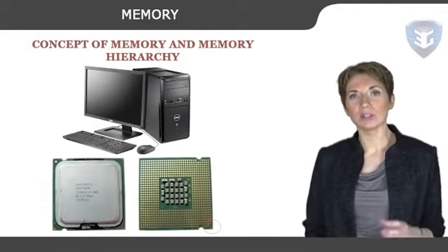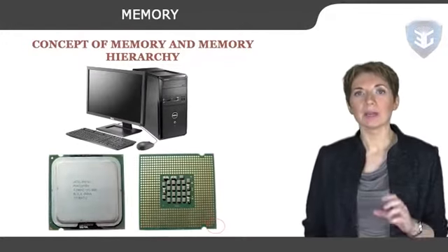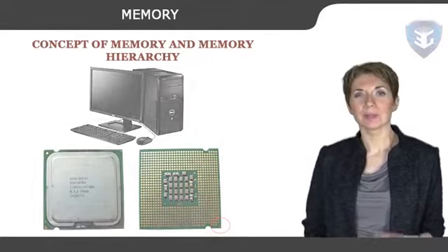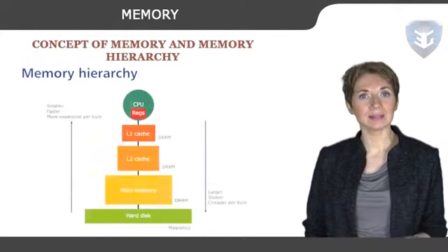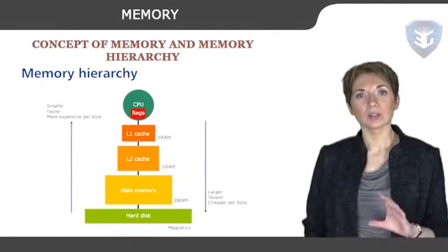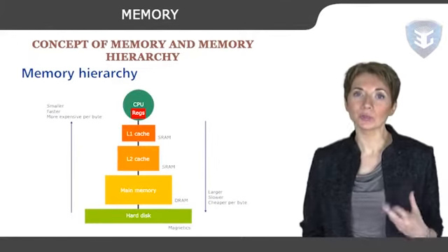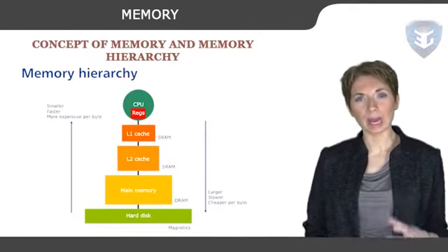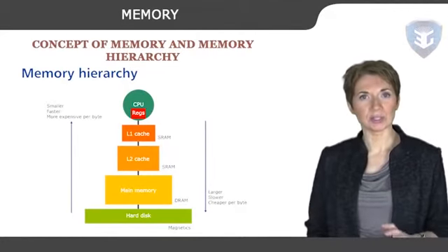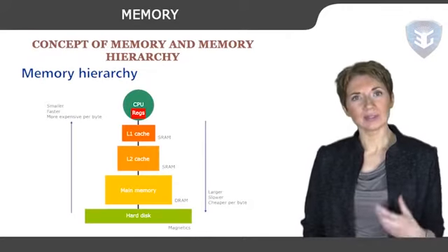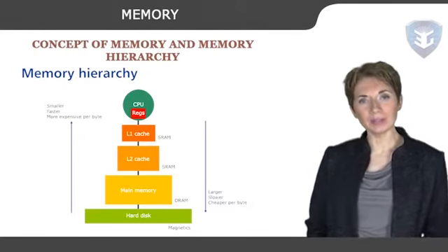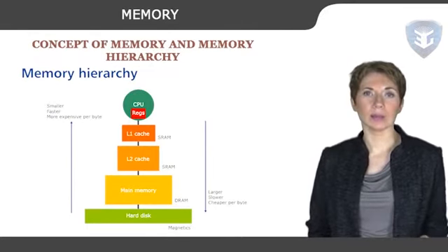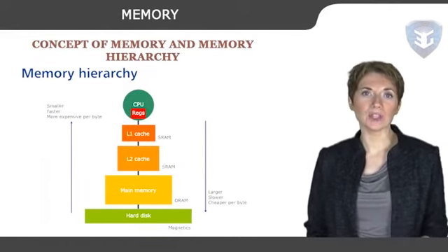But does this kind of technology, where there is no speed gap between the processor and the memory speed, exist? Yes, it does. But unfortunately, as the access time becomes less and less, the cost per bit of memory becomes increasingly higher. In addition, normally these memories require power supply till the information needs to be stored. These things are not very convenient, but on the other hand, the memories with smaller cost have very high access time that will result in slower operations of the CPU.